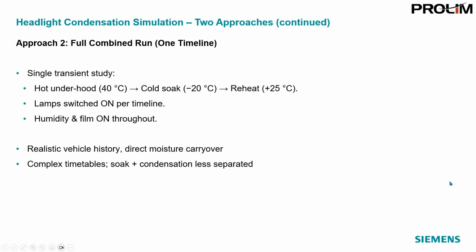And the other one is what we just did, which is a combined approach in a single timeline, where we heat the underhood, then we cold soak, and then we reheat. So all of that combined into one is what we have done in this specific simulation, where we consider lamps turning on and then we turn on the humidity and film as well. Now, the second approach is more realistic vehicle history, but sometimes it can get complex to simulate both cold soak and condensation at the same time.